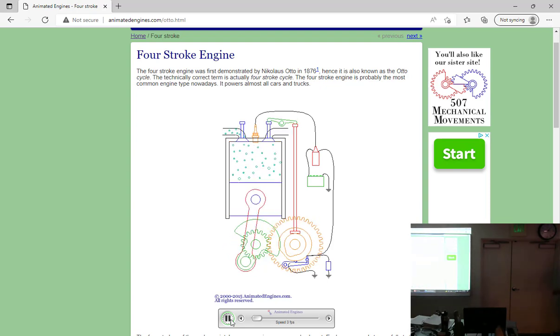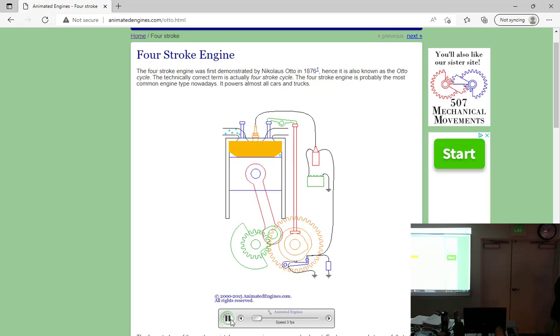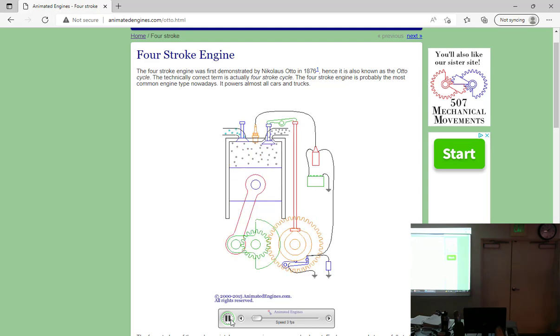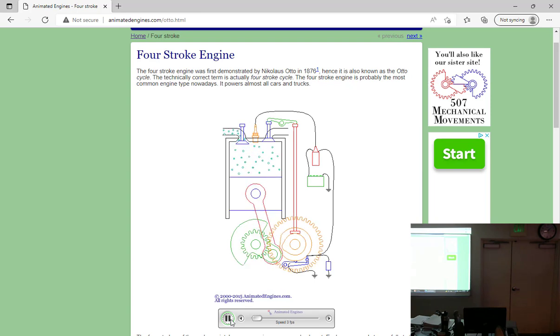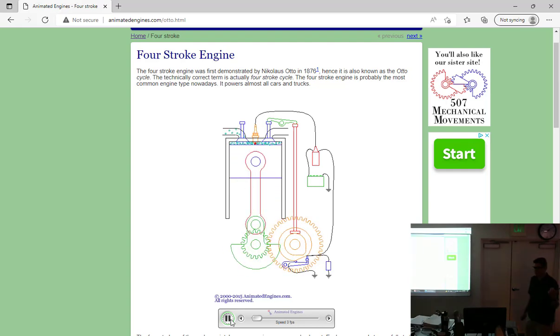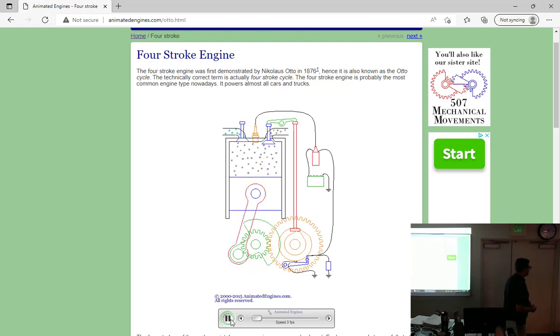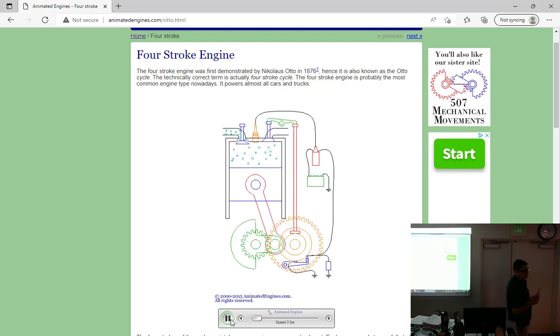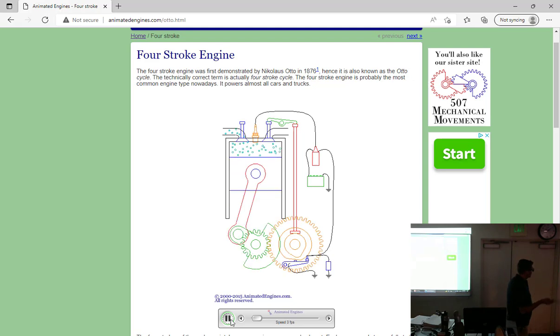The cam is the thing that has to open and close the valves. In this application, to make it right, they would have to draw it in another way, because you have to have the same mechanism, a rocker arm over here riding on a cam. So we could have put dual cams on here. Engines, some have dual cams. But you can see that this has to know when to open that exhaust valve. And it only opens that exhaust valve every other rotation. So the crankshaft is spinning twice as fast as the camshaft.